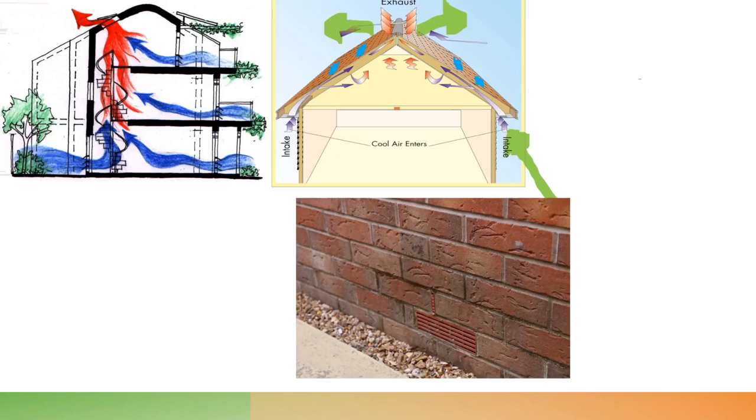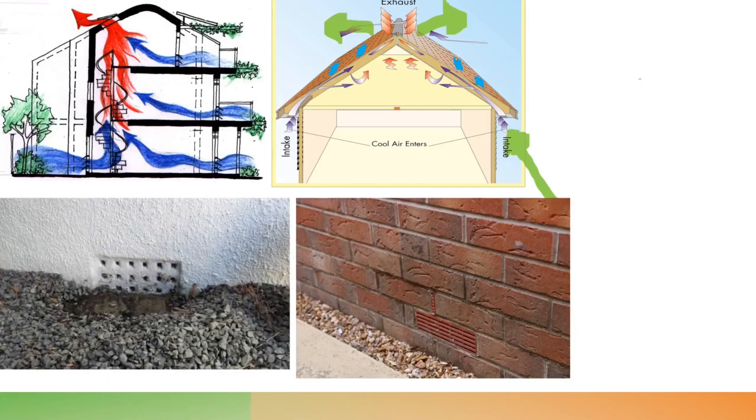And when I did actually go and survey it, most of the condensation was at the top of the walls, underneath the underside of the ground floor joists. So what that indicated, when I first got there, there wasn't an air brick at the front of the house, and neither was the one at the back. Oh, sorry, there was one at the back, but it looked like this.